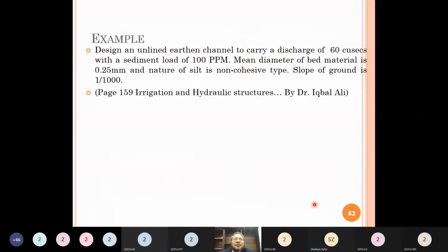These permissible values are on an experimental basis? Yes, of course. These have been determined in experiments in very big flumes, in which we could change the slopes, etc., and by changing the material in the bed and sides, and by physically examining the movement of sediment on the bed, when a sediment particle starts moving.